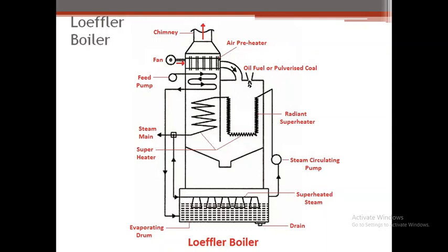It is nothing but an extension of the Lehman boiler, but the difference between the Lehman and Loeffler boiler is that the Loeffler boiler can generate steam with the use of salt water, and there is no problem of salt and sediment under the boiler. But in the case of the Lehman boiler, if it generates steam from salt water, there is a problem of salt and sediment on the boiler surfaces.